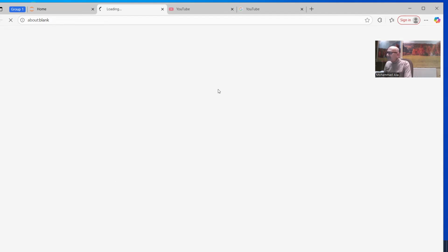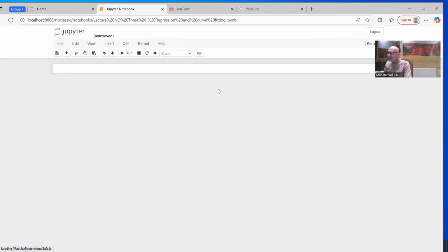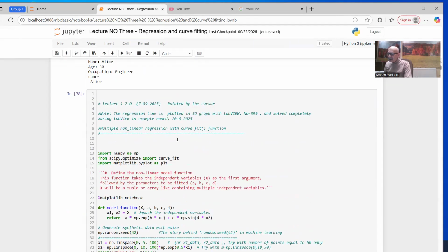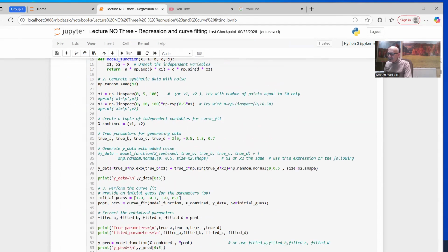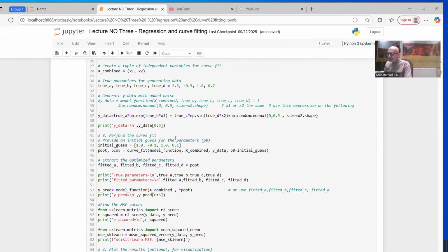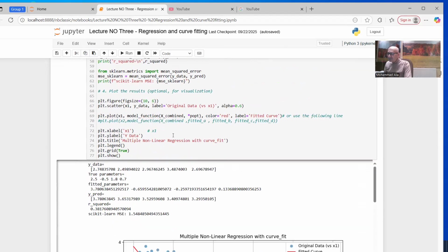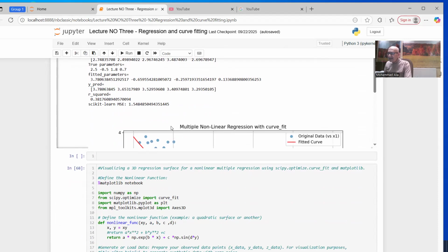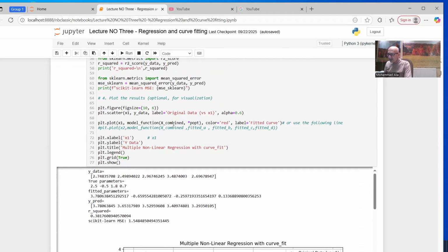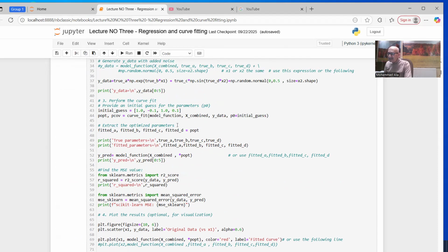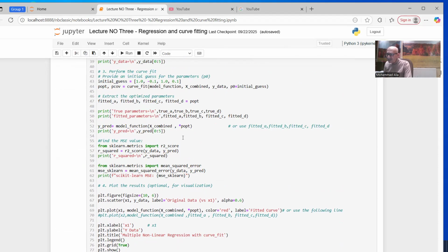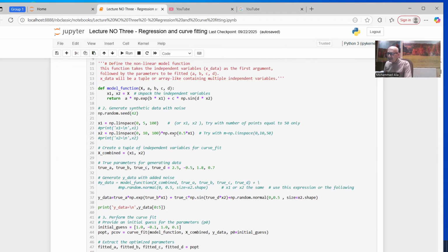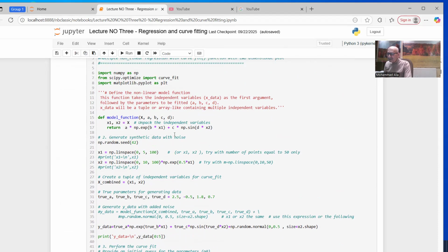Another simple way is to save the required Python data as a CSV file in Python, and after that convert the CSV file in LabVIEW, because LabVIEW can open and convert CSV files as strings or as data containing double precision values.